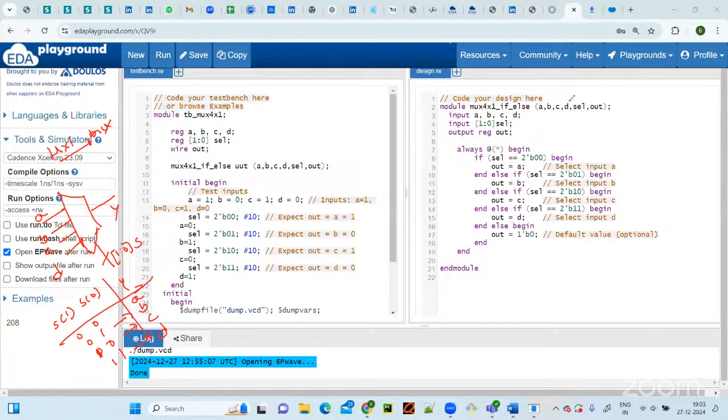That is what you can see here. Initially, I have taken all the necessary input and output ports and given directions to them: input A, B, C, D, input [1:0] SEL, then output out. As it is behavioral modeling style, all output variables must be declared as reg. It is mandatory. How many selection lines are required for a 4x1 mux? I need two selection lines, right? That is the reason I have taken two selection lines.